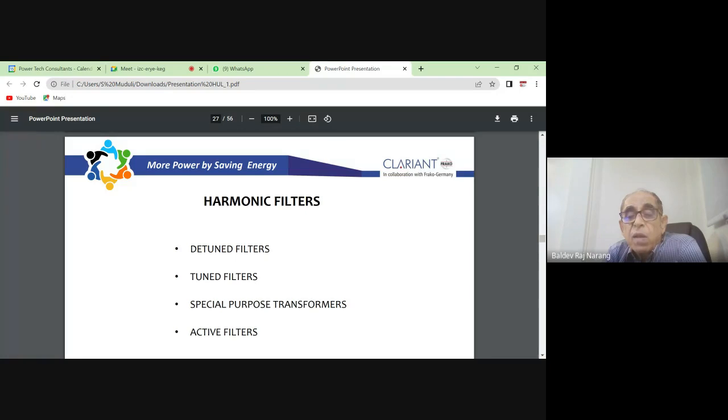Normally in the market, people will give you power factor correction with a passive APFC system, without guaranteeing any harmonic mitigation. And they will ask you to put an active filter for the harmonics. So the two systems are given, passive for power factor, active for harmonics, but it is actually not required. We can design the passive systems and many times it may be sufficient to do away with active altogether. We can do 100% mitigation with passive also.